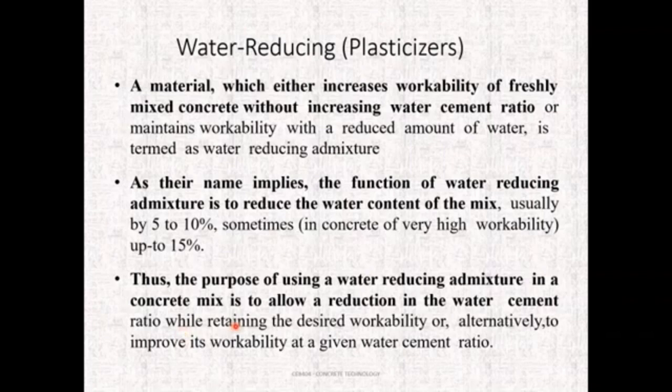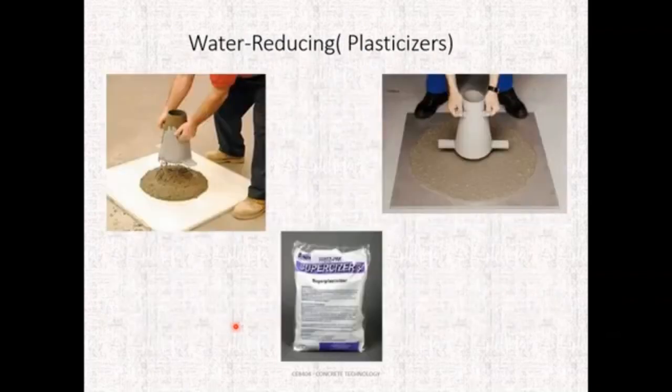Generally, during the design mix, we will increase the workability by adding additional water. By using plasticizer, we can maintain the same water cement ratio for different mixes. This is the action of water reducing agent. It will increase the workability, that is, the flow of the concrete.